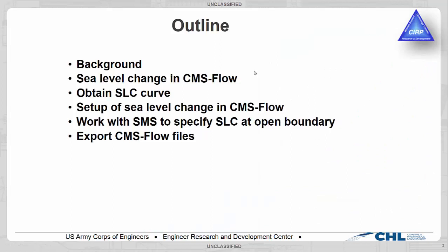Again, the outline of my presentation: first some background information, and then sea level change in CMS-Flow. After that, I will show how you can get your sea level rise curve, and how to set up this sea level rise change in CMS, and then work with SMS to specify sea level change at the model boundary, and then save the file and make your simulation.